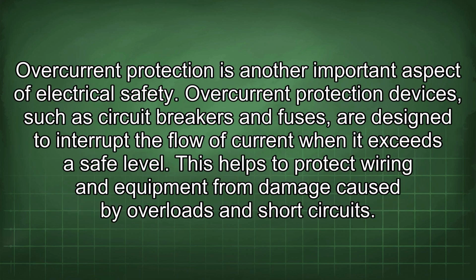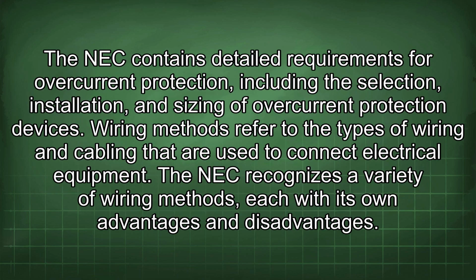Overcurrent protection is another important aspect of electrical safety. Overcurrent protection devices, such as circuit breakers and fuses, are designed to interrupt the flow of current when it exceeds a safe level. This helps to protect wiring and equipment from damage caused by overloads and short circuits. The NEC contains detailed requirements for overcurrent protection, including the selection, installation, and sizing of overcurrent protection devices.